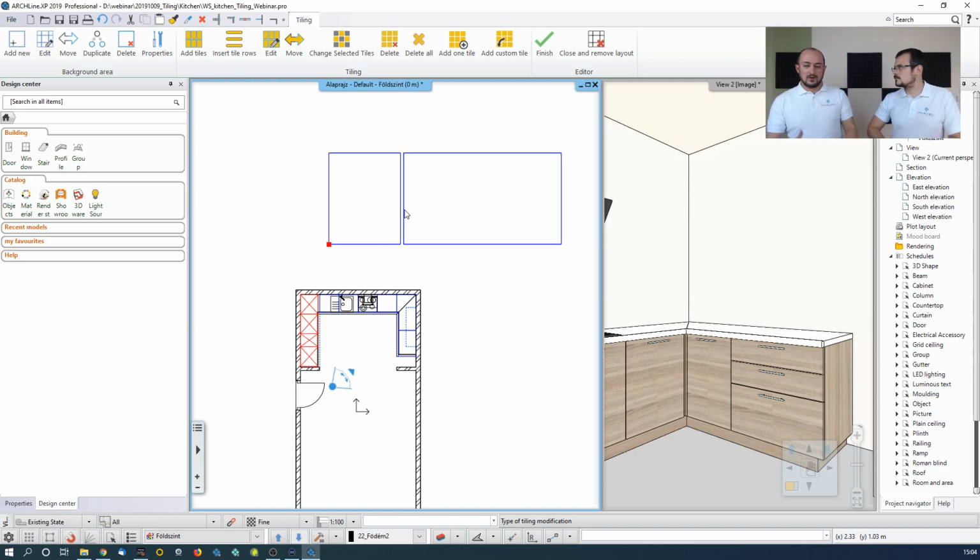So this means when I use this tool, I can place the whole wall layout, even if it's intersected with different smaller walls or something like that, in one go, and I can work on the full surface at a time. Now, once you place this layout, right after that, you will see those commands appearing at the top of the screen. Those are the tiling commands. The first thing first, you will see the first 5 or 6 commands here. Those are color-coded in blue.